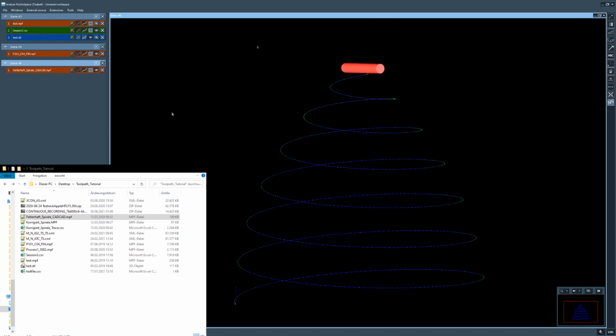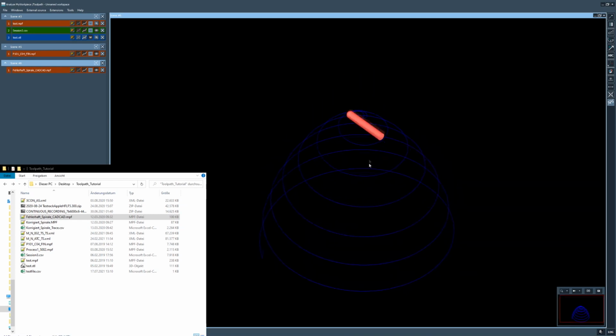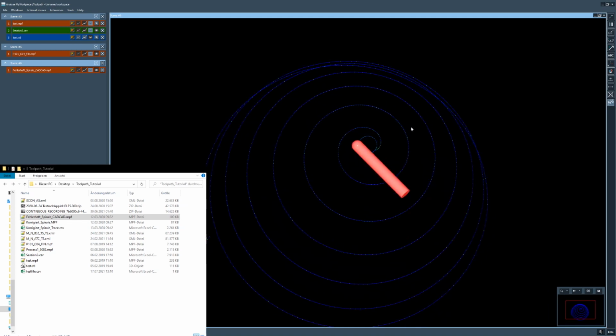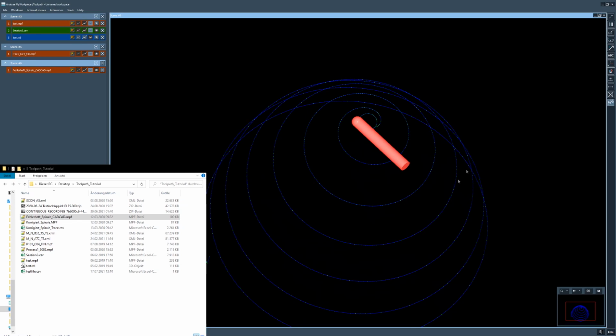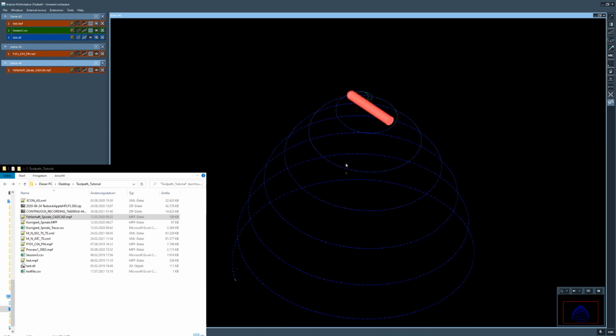And this will also help you to understand what is going on in the part program and whether this is really what you want to have. And it's obvious that when machining these last circles, the mechanic will definitely run into stability issues, and also the controller will slow down the whole execution. So this T-tab gives you a different impression of the point cloud and what is going on there.